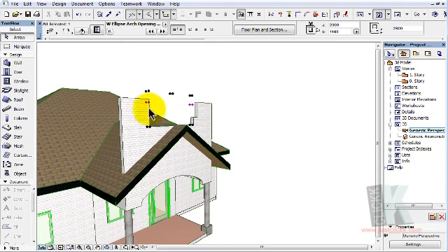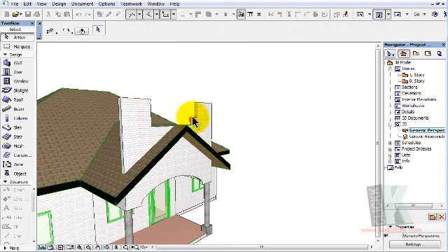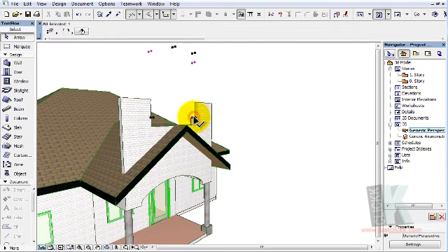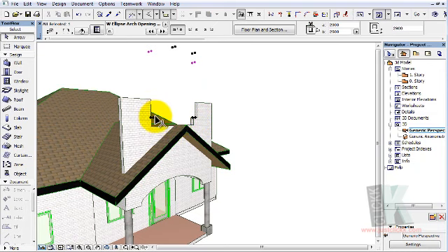That's why the wall is being chopped up like this. So let's select the arc tool and delete it. There are some existing arc tools here. So I've deleted one, and I'm deleting the second one now. By the time we are done deleting them, you will see that this wall will level up there.